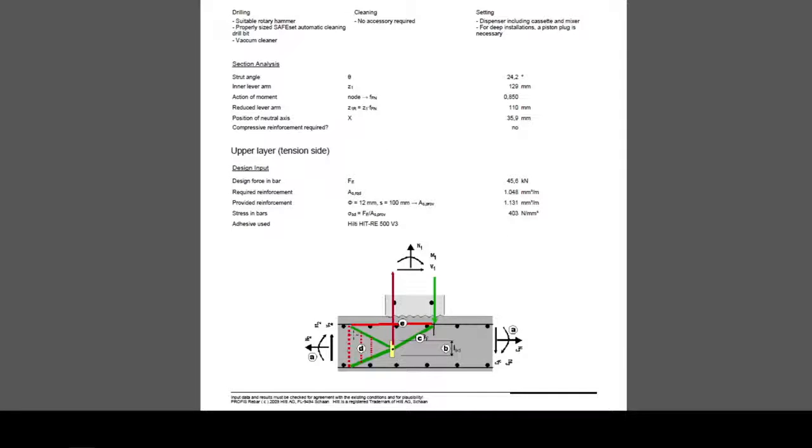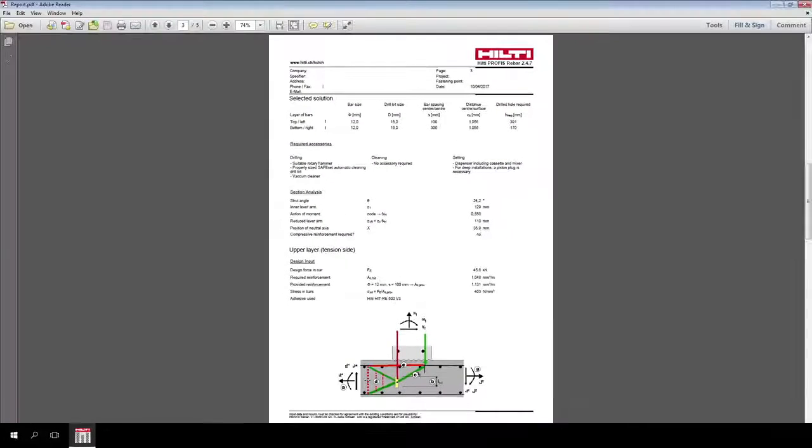The software verifies that the compressive stress transferred in the diagonal direction is equal or smaller than the compressive strength of the concrete. Paragraph D verifies splitting in the transition area. For equilibrium, the concrete is subjected to tension in the vertical direction. The software verifies that the splitting stress developed in the slab is equal or minor than the tensile strength of